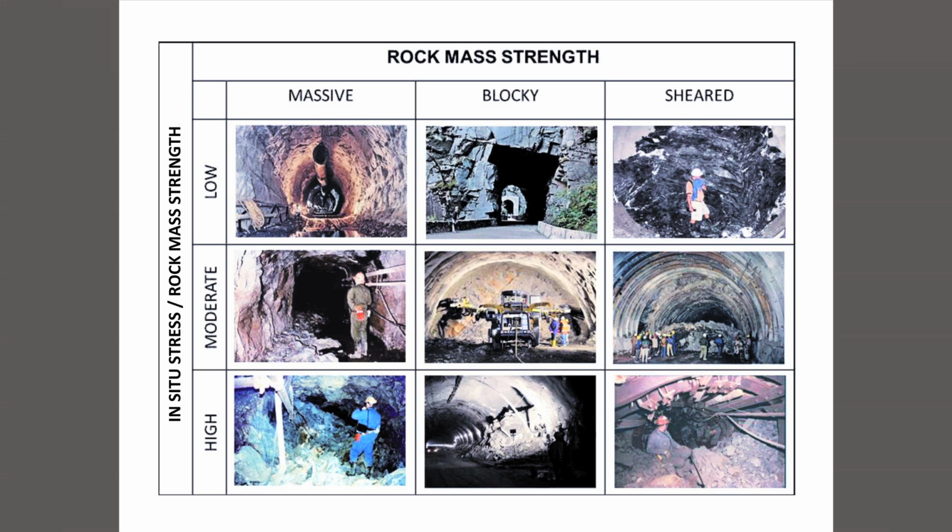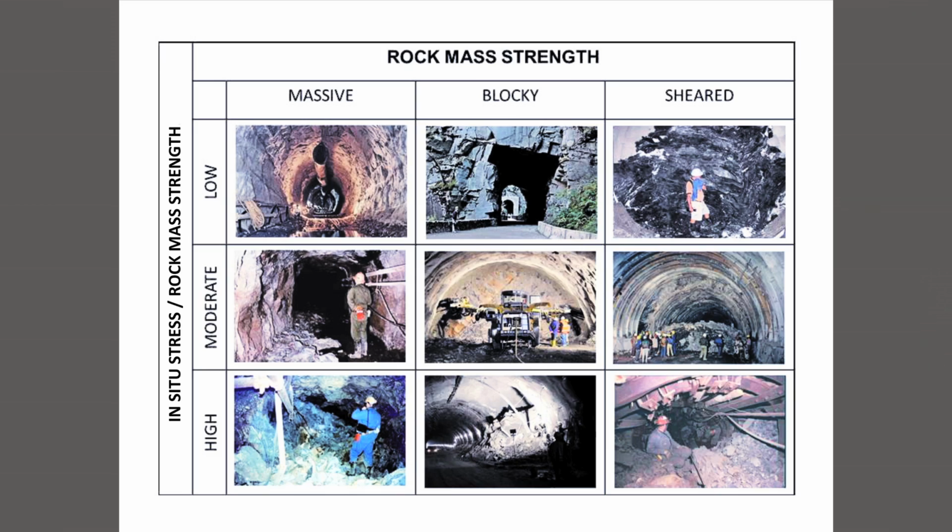And then as you work your way down that column on the left, as the tunnel gets deeper and deeper, the stresses get higher and higher, and if you get down to 2 or 3 kilometers below surface, you can expect to get conditions where the rock will fail pretty catastrophically, and in the worst case, what we call rock bursts.